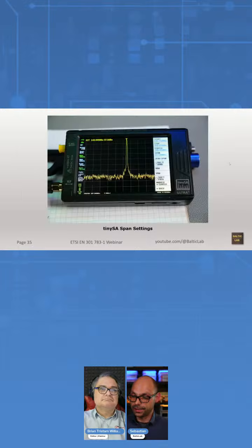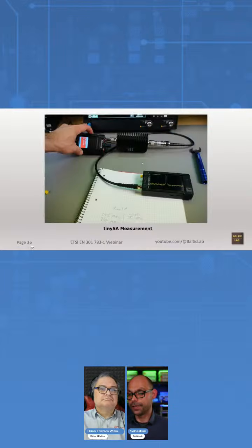That said, you also need to make sure that your span, which I've shown here as 22.5 megahertz, matches the 450 points that the TinySA Ultra Plus has, divided by the 100 kilohertz, and that divided again by 2. And then you have to cycle through and measure every harmonic individually. Interestingly, I actually did that comparison earlier, although I didn't put it in the slides.